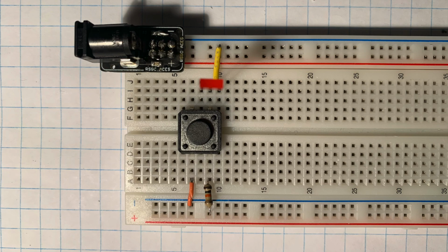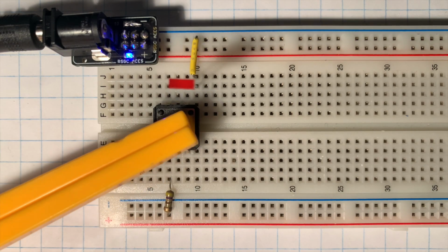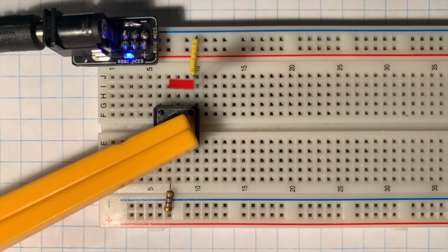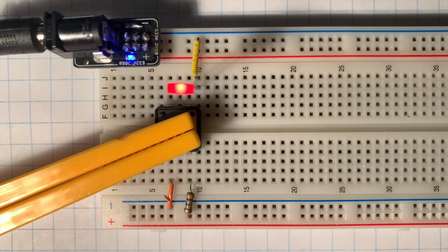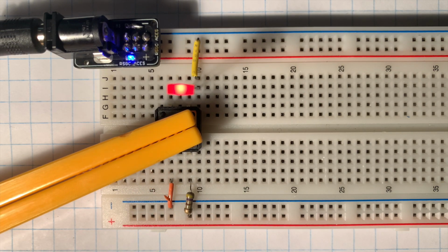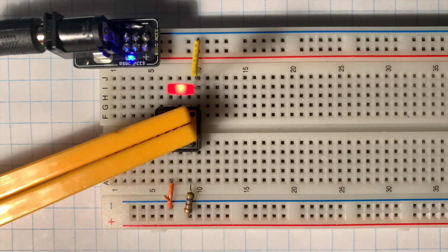A counting circuit starts with a button input. There are two options when doing a button input, a high or a low side switch. The first is a high side switch, which when pressed, the output is a high. The second is a low side switch, which when pressed, the output is a low. This circuit uses a low side switch.